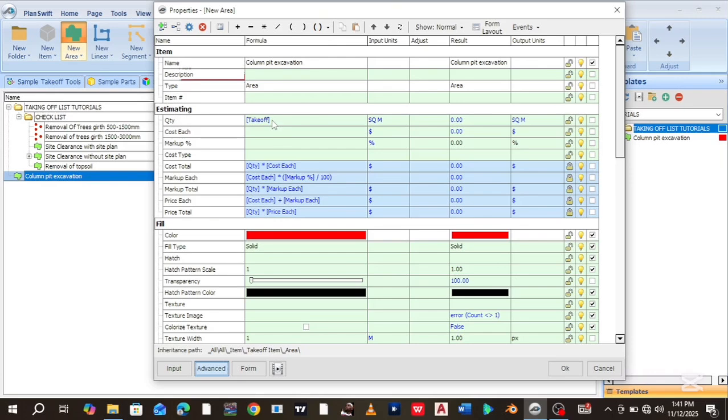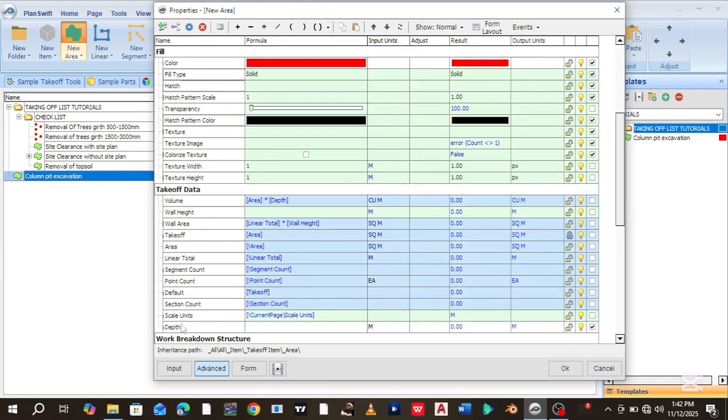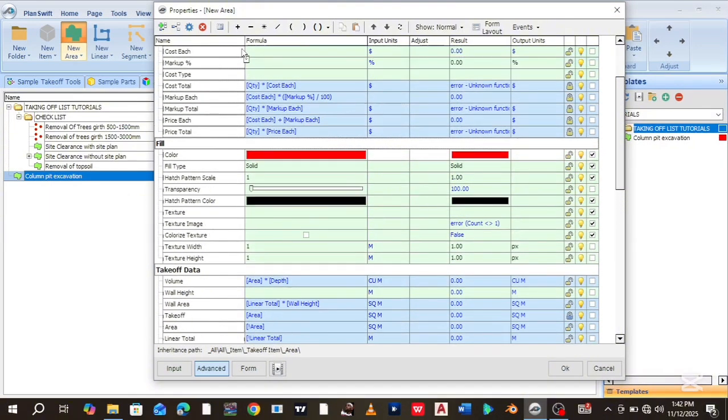So all you just need to do now is to click on this formula section here on the quantity tab, and then you see this place that you have asterisk, which in computer language means multiplication. So you enter multiplication. The place where you dropped that depth, you go there, copy it and move it to the quantity tab there.